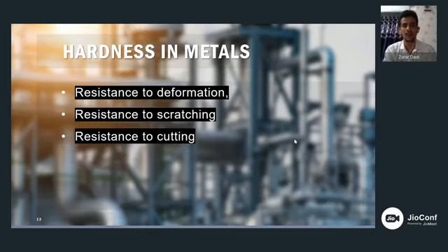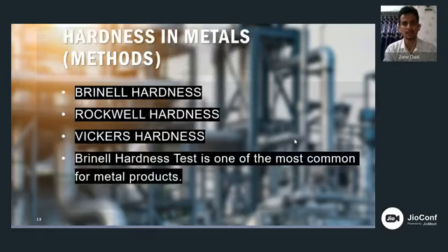If we want higher strength, then the material should be ductile, as it elongates up to a higher load. But let's see hardness, how we derive hardness, and then we'll discuss how these properties are important. There are many types of hardness methods, but Brinell and Rockwell are widely used, and some industries ask for Vickers hardness as well. But in industries, mainly Brinell hardness is required.